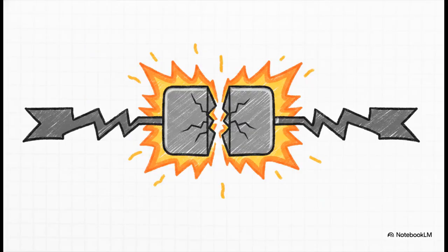But notice how that graph eventually drops off sharply on the far left side? You definitely want to avoid pushing the reverse voltage too far into what we call reverse breakdown. If you pull on those electrons hard enough with a massive reverse voltage, they'll violently tear right through the junction. And unless that current is strictly limited, the resulting heat will permanently melt your diode into a piece of useless slag. No coming back from that.